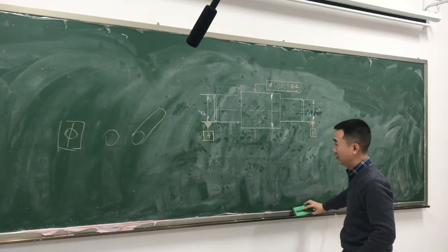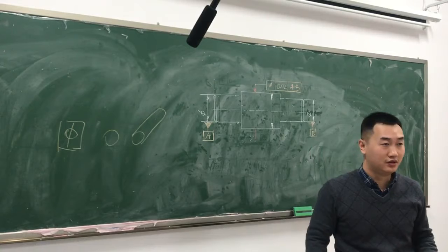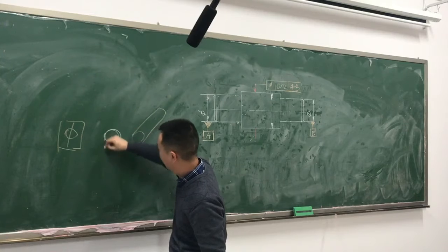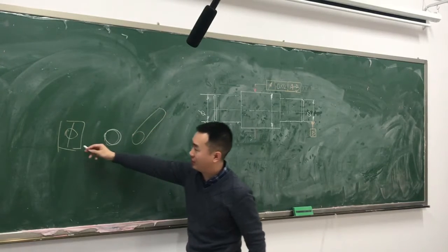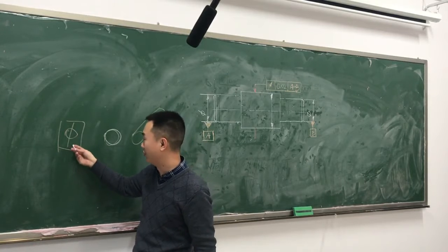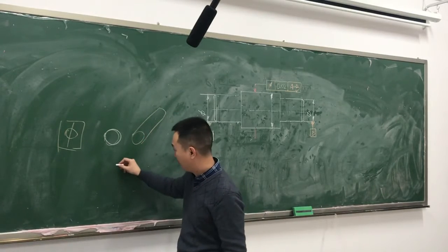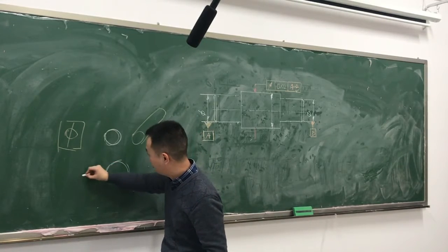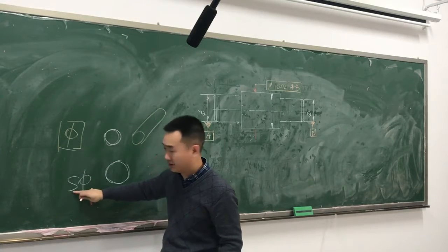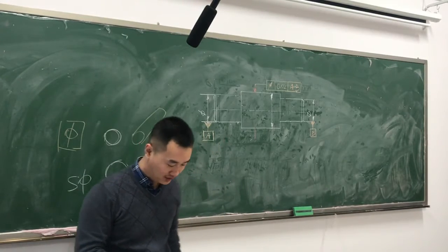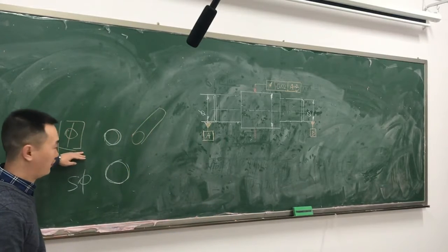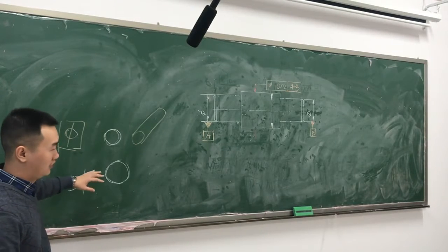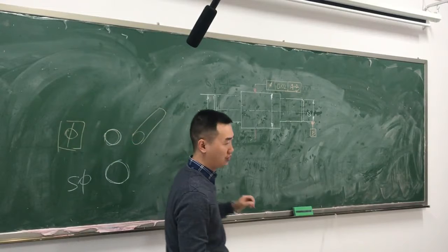Okay. So that's if it's a circle or a cylinder. If the tolerance zone is a circle or a cylinder, you should put a phi symbol before the value here. And if the tolerance zone is a sphere in space, then you should put an S phi. It means sphere. So when you see a phi diameter symbol, phi or S phi, you should think about whether the tolerance zone fits. Okay.